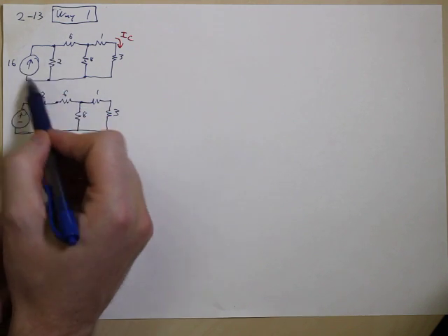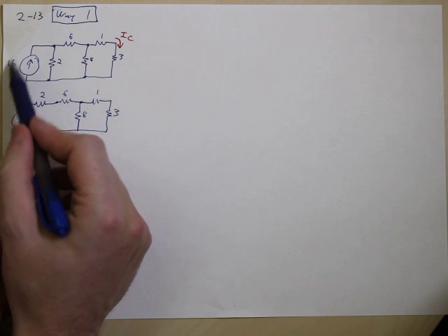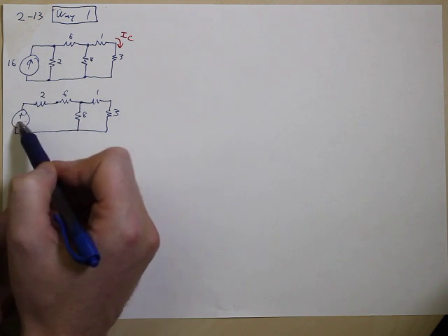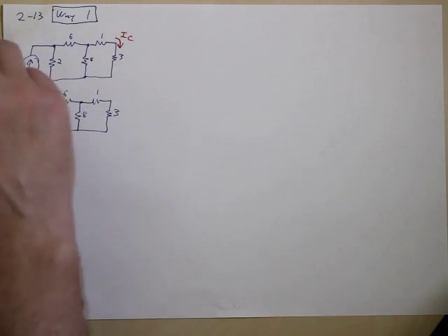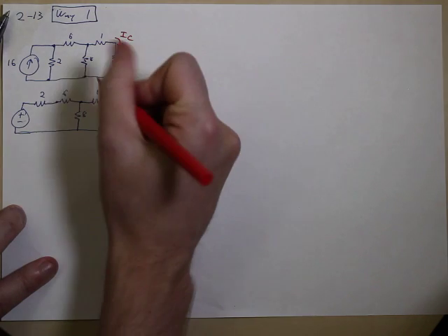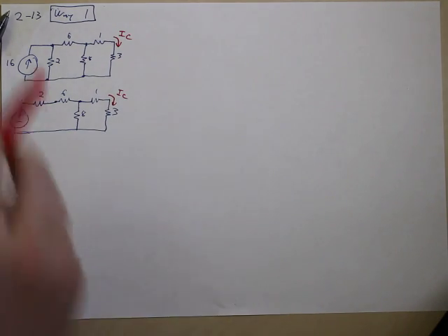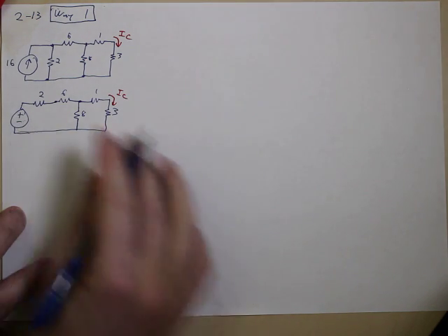We just took this entire little bubble thing, this current and resistor in parallel, and we made this a voltage source and a resistor in series, and the rest of the problem stayed the same as up there. And so again, I'm just going to make the IC going through here because we know that's what we're looking for still. And then the other part that's important is, what is this new voltage source? What is the value of it?